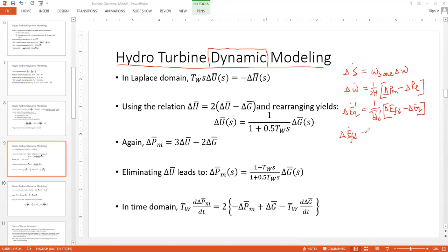And the fourth state variable was the exciter dynamics, del V ref minus del VT. So these were the four state variables. And in that model, up to this point, we considered two input variables, del PM and del VREF. But once we did it in the last class, we can clearly see that we have the fifth state variable arriving here in the form of del PM.